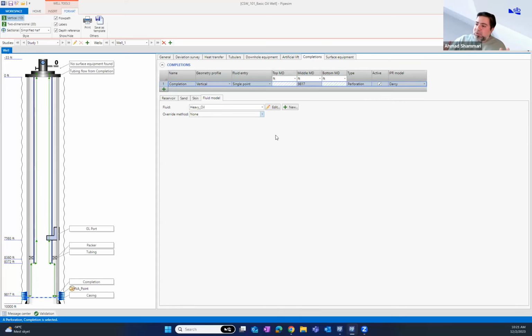In a network model, you could have, let's say, one fluid file that is shared among maybe 30 or 40 or 50 wells or 100 wells, for example, okay? However, each well might have different GOR and water cut. So you can go to that well locally and override the phase ratio, okay?